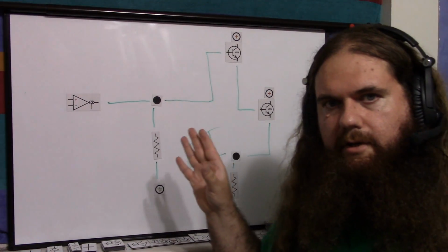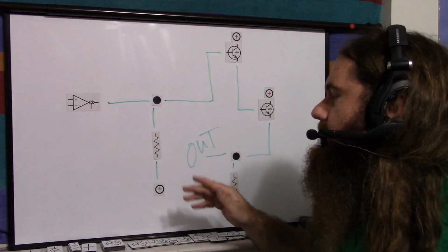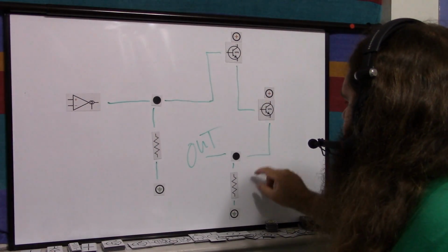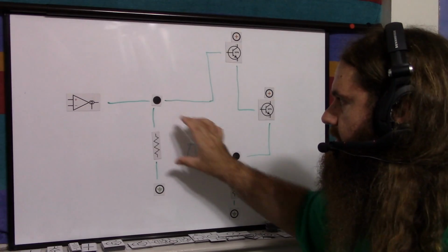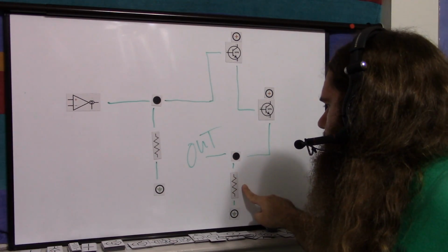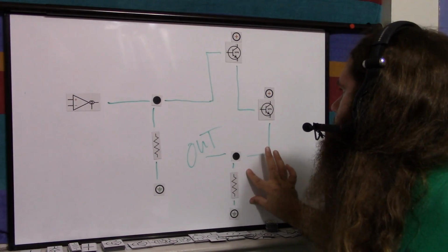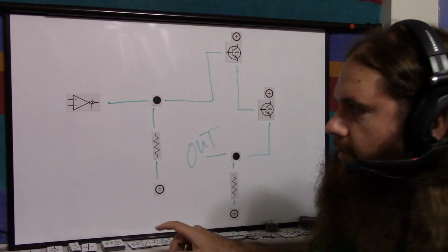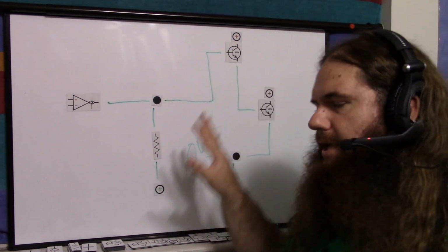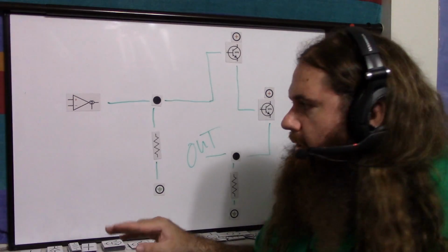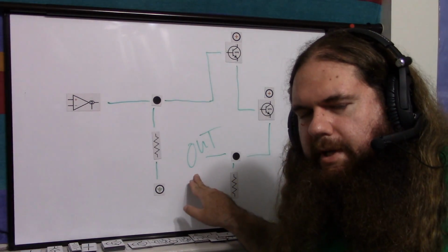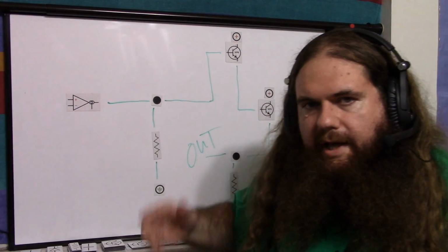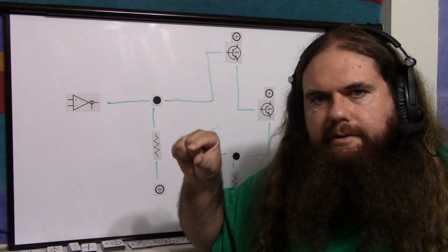I need to do a video proper on voltage followers, but the trick is basically the current goes through here, you get a voltage, which biases base to emitter, it biases this resistor to the same voltage, so you get whatever current makes the same voltage drop here and here, plus the base to emitter drops. So the voltage here follows the voltage here. This is setting the current, but the impedance doesn't appear to change, because whatever varying impedance, whatever power draw you have throughout, is fed by the collectors. So that's the buffer, and it's right there on the chip.